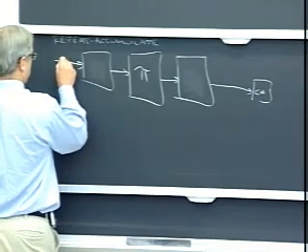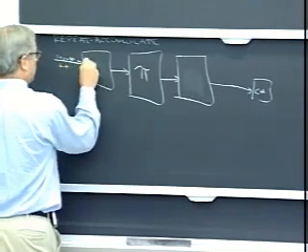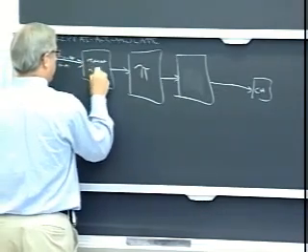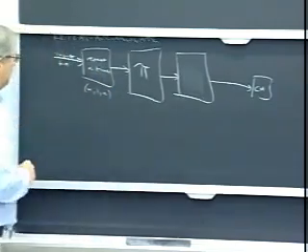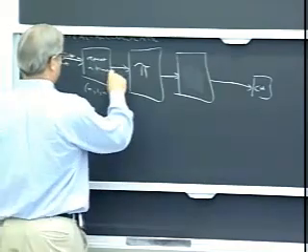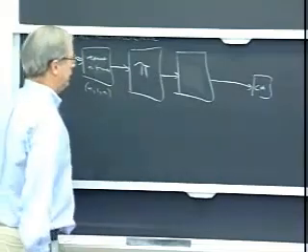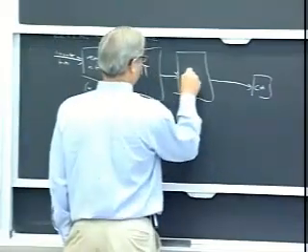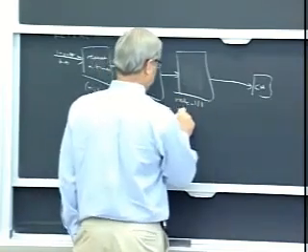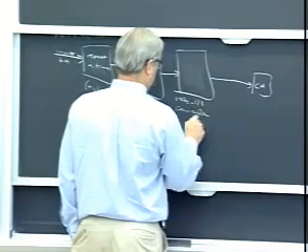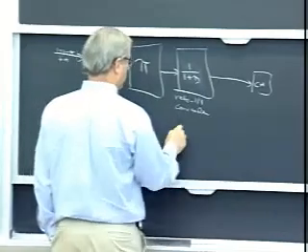We take input bits here. We repeat n times. So this, if you like, is an (n,1,n) repetition code. That's pretty simple. We have a stream. In a long block, we would then permute everything within the block. And then this is a rate 1, or 1 over 1, convolutional code called an accumulator. This is the code with transfer function 1 over 1 plus D.